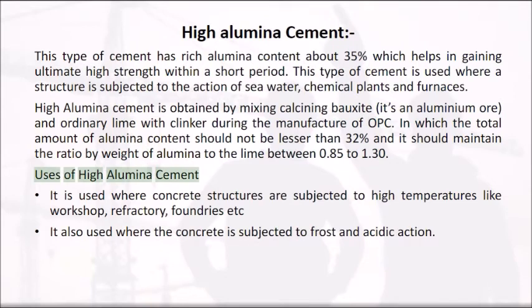Uses of high alumina cement. It is used where concrete structures are subjected to high temperatures, like workshops, refractory, foundries etc. It is also used where the concrete is subjected to frost and acidic action.